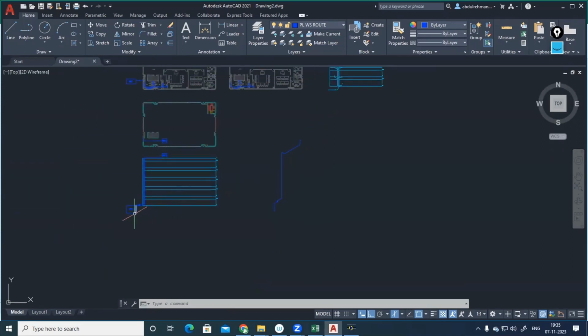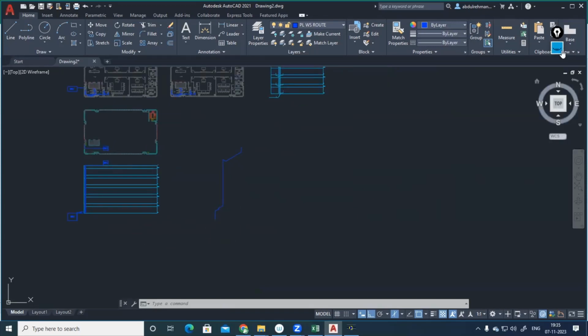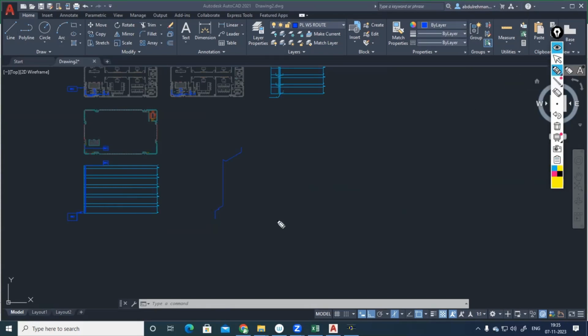Anyhow, see when we are placing the pump, this is your underground tank. Okay. This is a water level. If the pump has placed above the water level, then this suction pipe we have to fill with the water. Because inside the pipe, air should not be there.